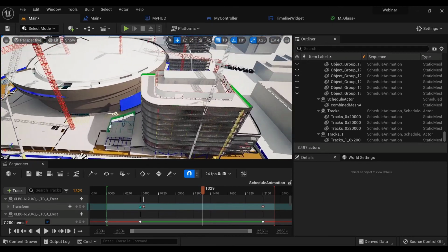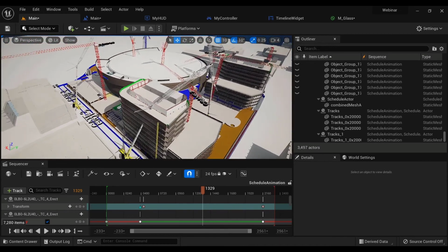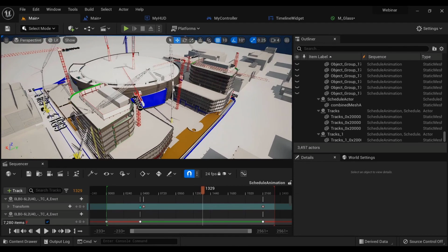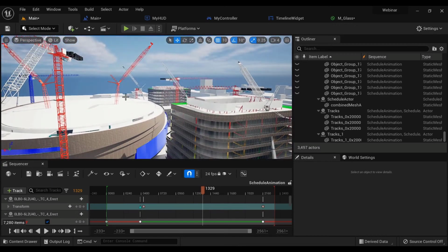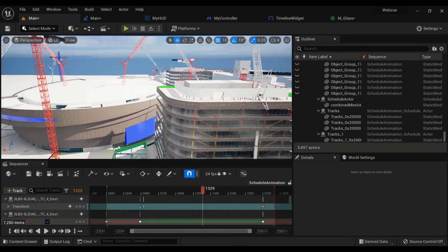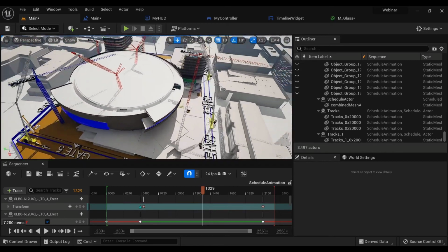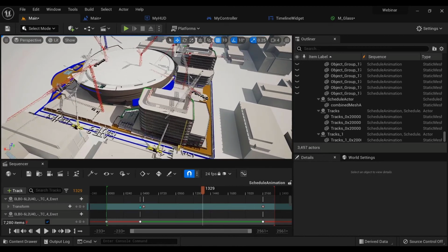You could even put this in a data prep recipe, and even though data prep recipes, like I said, aren't great for combined meshes because so much stuff isn't there, you can still set up a material substitution table, and then if you ever need to re-import this stuff, get all your materials placed in the correct material slots instantly. So that'll make it a lot easier and faster, and that's a great thing about having the integration with the Datasmith pipeline.